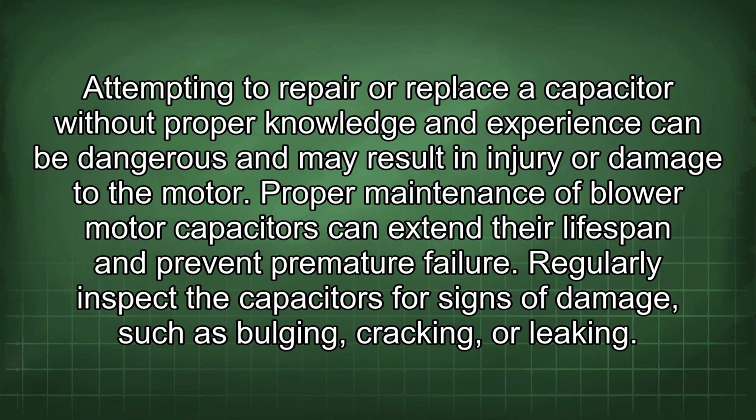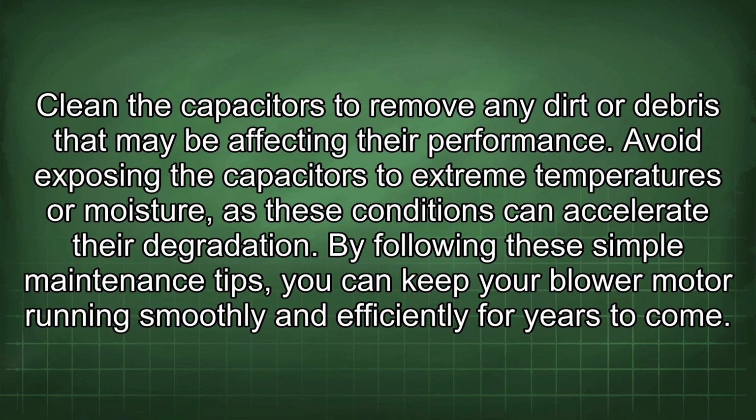Proper maintenance of blower motor capacitors can extend their lifespan and prevent premature failure. Regularly inspect the capacitors for signs of damage such as bulging, cracking, or leaking. Clean the capacitors to remove any dirt or debris that may be affecting their performance. Avoid exposing the capacitors to extreme temperatures or moisture, as these conditions can accelerate their degradation. By following these simple maintenance tips, you can keep your blower motor running smoothly and efficiently for years to come.